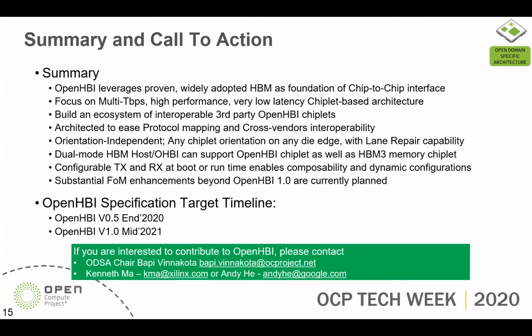So you can then build a design for memory intensive applications for one SKU, and then you can build an IO intensive or accelerator intensive one for a different SKU. Configurable TX and RX, set either at boot time or runtime, enable composability and dynamic configuration. Again, this should be pretty useful when you have many different workloads to deal with. Substantial figure of merit enhancement beyond OpenHBI 1.0 is currently planned. So for now, we are planning the version 0.5 specification by the end of this year, and then version 1.0 by the middle of next year.